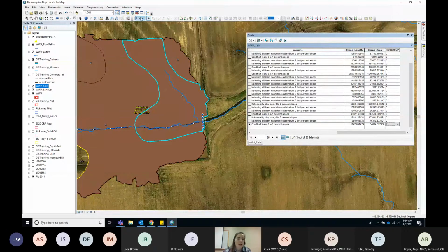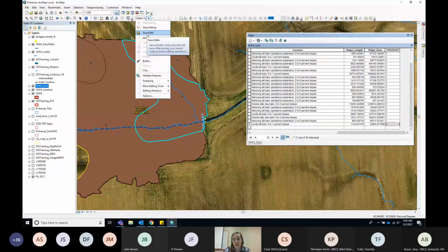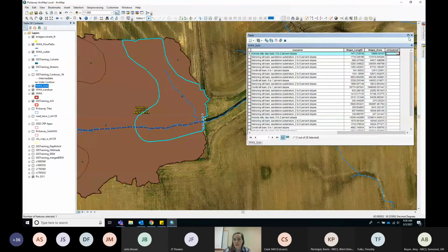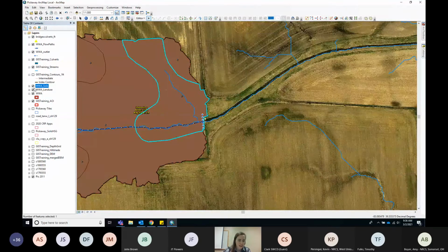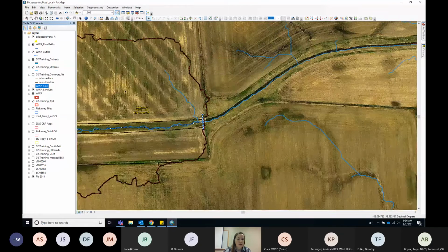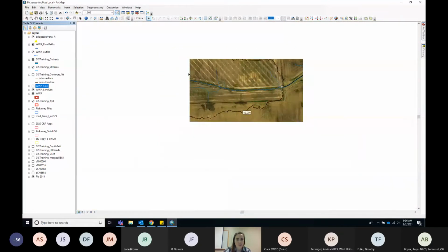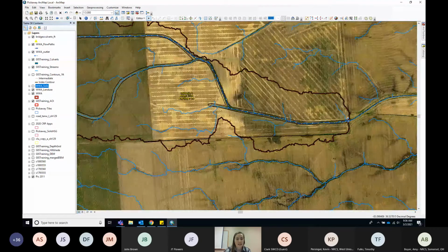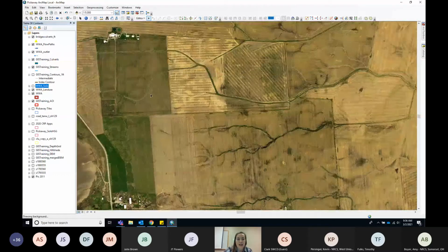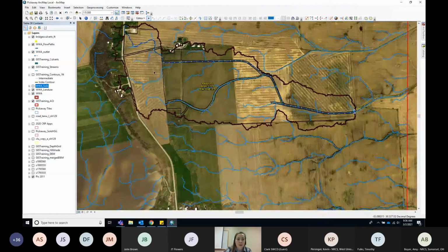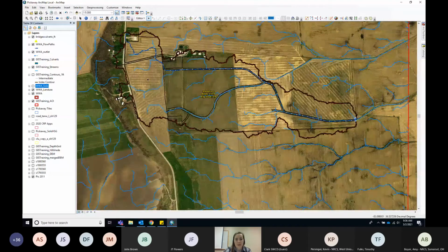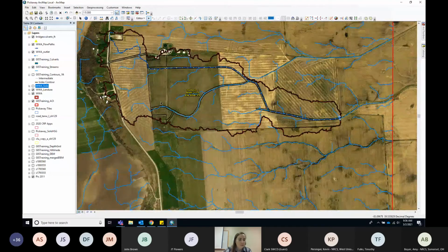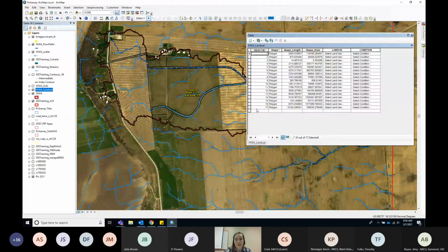And it's good practice to go ahead after you've edited everything here. You just go ahead and say save edits. I wouldn't stop editing though, because we also need to edit our land use. So here's, if you have your clue layer, this is where it comes in handy. So it's black lines, but you can see where borders changed based on the clue layer, and you're going to decide what type of land use that is based on those blocks. So I'll go ahead and open that attribute.